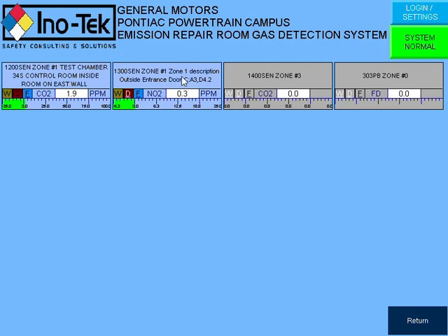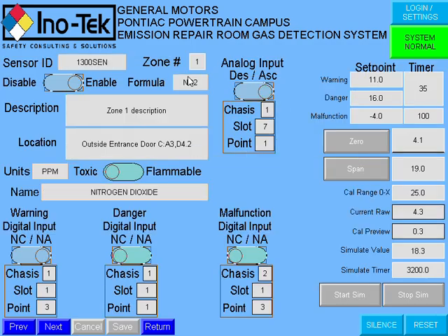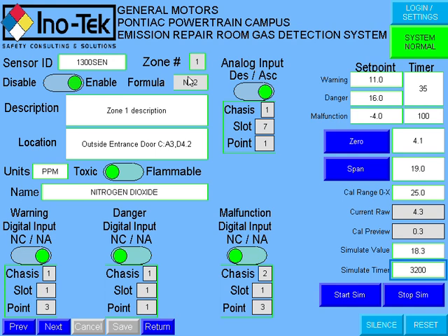So when you hit here, this is going to be the sensor configuration. Every sensor should always have an ID number, so we can use the same sensor name on the drawing. It's going to be easier to recognize which sensor we're talking about, instead of having sensor 1 or 3 and so on. For sensor 1300, you can go to the drawings and find that sensor there.